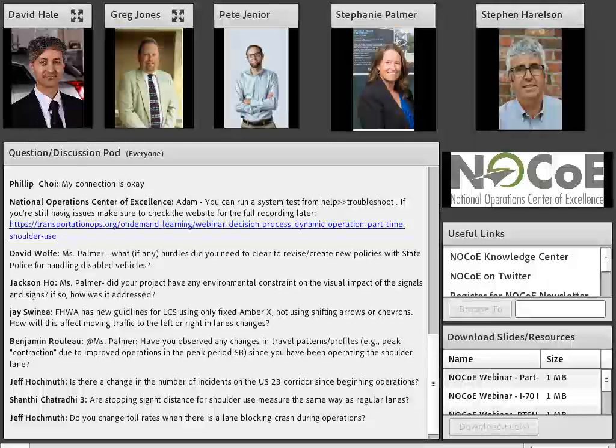The studies to date have been somewhat limited. They've usually been facility-specific, and there are always changes in volume associated with part-time shoulder use, not necessarily daily volume, but volume at different hours of the day. So it can be hard to isolate the effects of shoulder use from some of those other things. There is an NCHRP project ongoing at this time that will better answer that question in a couple of years, specifically about part-time shoulder use safety. So I'd say for now it's really been a mixed bag.